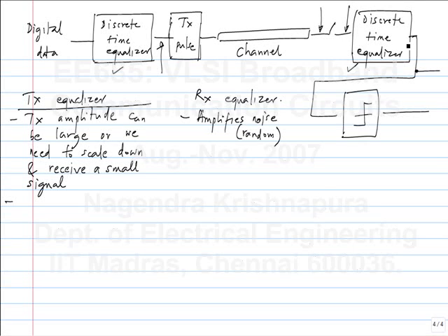If we have the equalizer in the receiver, then we can look at the output of the equalizer and adjust its taps. But if we have it only in the transmitter, then we can only look at the signal on the receiver side, and we have to somehow send back information to the transmitter side to adjust its taps. And this transmitter and receiver may not be at the same place. That's the idea, right? That's why you have the transmitter and the receiver. There are certain channels in which you use the same pair of wires in both directions. But how do you start off? There has to be some information going the other way, just for adaptation, not for useful data.